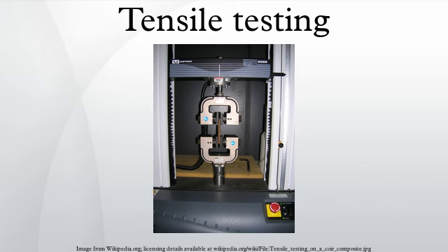Alignment of the test specimen in the testing machine is critical, because if the specimen is misaligned either at an angle or offset to one side, the machine will exert a bending force on the specimen. This is especially bad for brittle materials, because it will dramatically skew the results. This situation can be minimized by using spherical seats or U-joints between the grips and the test machine. If the initial portion of the stress-strain curve is curved and not linear, it indicates the specimen is misaligned in the testing machine.